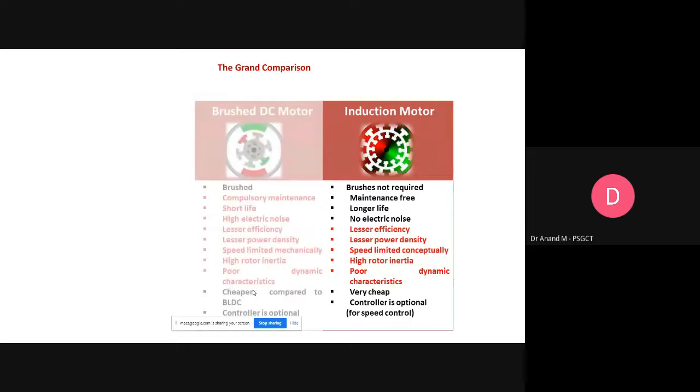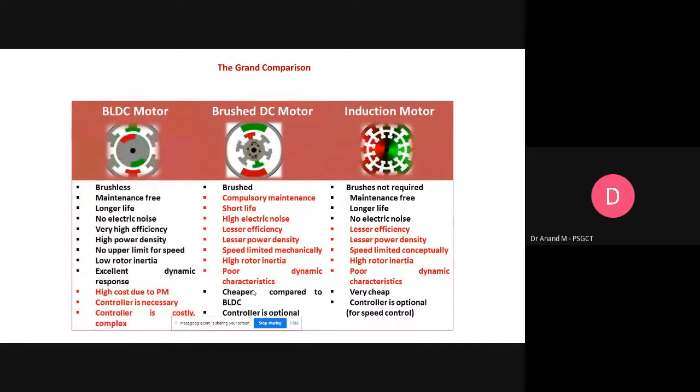The grand comparison of how the topology or how the electromagnetics came into the picture. Initially for traction, we used even the brushed AC series motors. But when it comes to the EV segment, due to the commutators and other hazards in the brushed motors, we thought of initially going for an induction motor. As we know, Tesla initially launched the EV segment vehicle with a three-phase asynchronous induction motor. Then why today, even in the four-wheeler, two-wheeler or tri-wheeler segment, does the research concentrate on the magnetic motors?